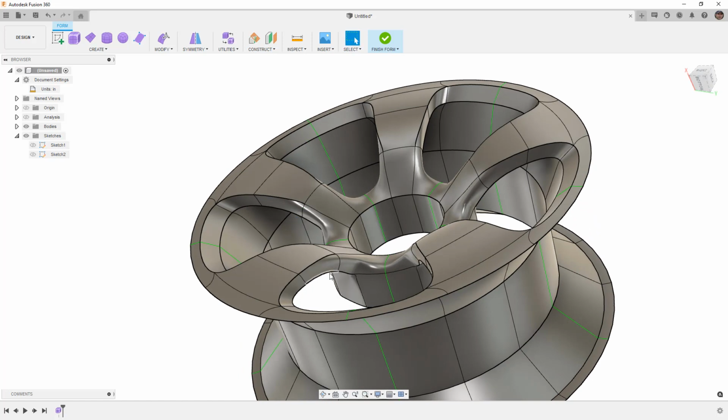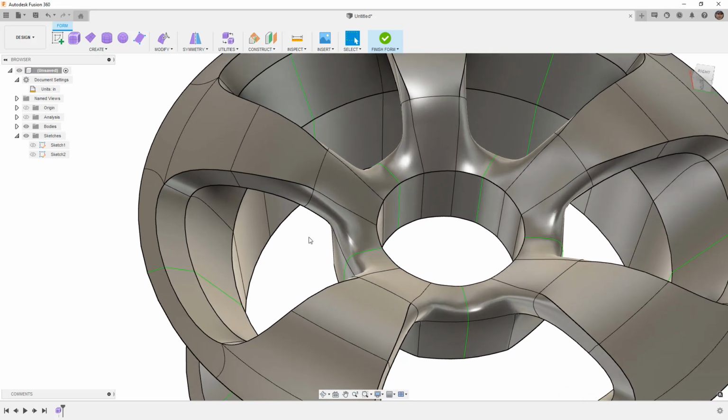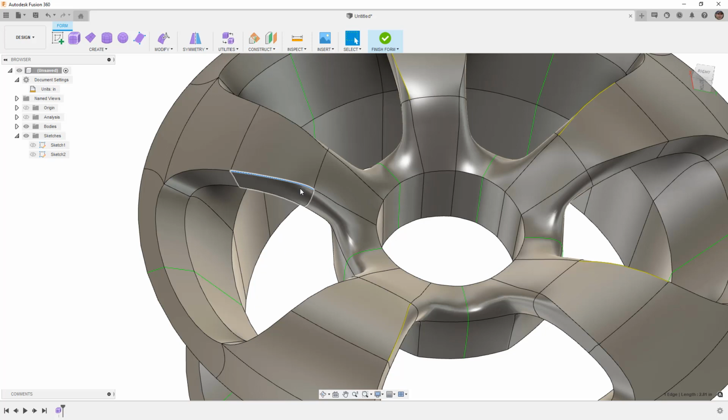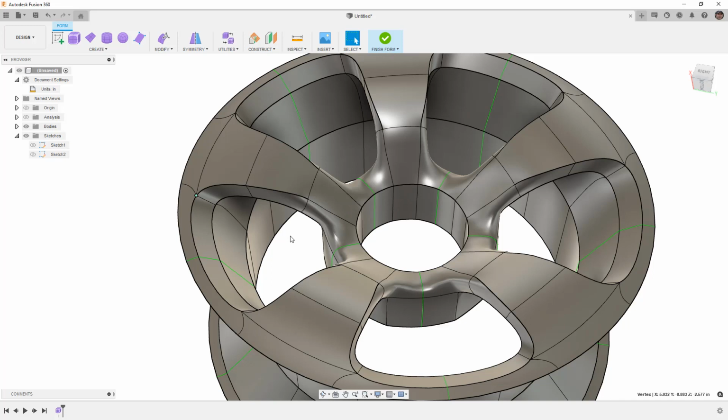I still don't really like these creased edges ending in a smooth edge. In my designs, I try to avoid that because I'm not really happy with the way that we can control the crease because it's either on or off in Fusion 360. Unlike other programs or other polymodeling programs or subdivided modeler add-ons for CAD packages, in some cases you will get an edge weight control. We could say that we want 0 down here and maybe 25% here and 90% here, but we don't really get that same level of control here. So we have to do it by inserting edges.